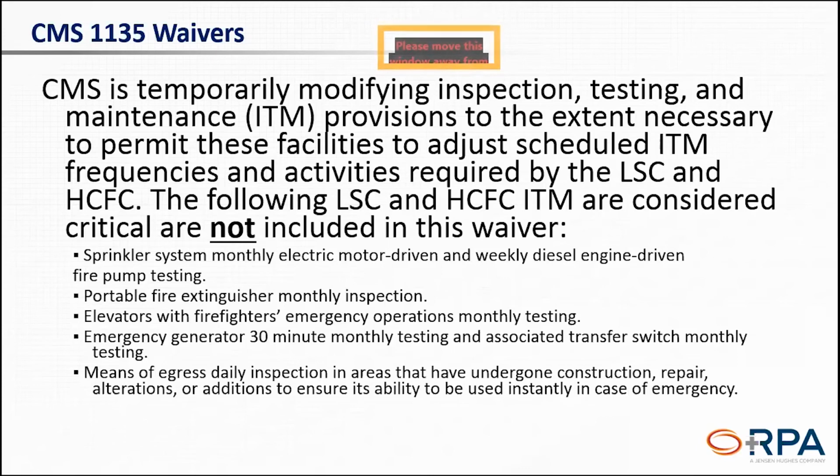Elevators with firefighters' emergency operations, so we can't reduce our testing for your elevators. You need to continue your monthly testing for emergency generators and associated switches, so you need to continue those monthly tests there. And then also, if you have any type of daily inspection rounds for any of your interim life safety measures, you need to maintain those daily inspections as you've self-declared.